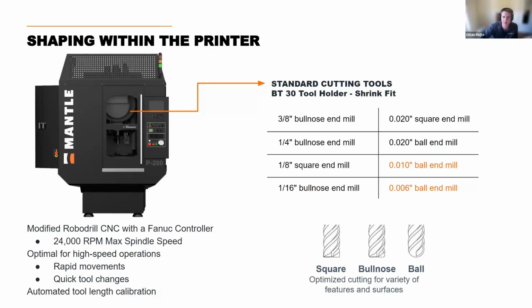These are all just standard off the shelf cutting tools, right? We don't make our own cutting tools and you can buy them from, I'm sure we have recommendations, but they're just standard cutting tools you'd use for other material. Yeah, that's correct. We've worked to find the right off the shelf cutting tools so that it's easy to source these tools. Obviously, our cutting of the green body is different than cutting of hardened steel, but we found the tools that work best for our process that are easy to get, readily available, and they fit inside of standard tool holders as well. And so this whole part of the process will be very familiar to people who do CNC machining.